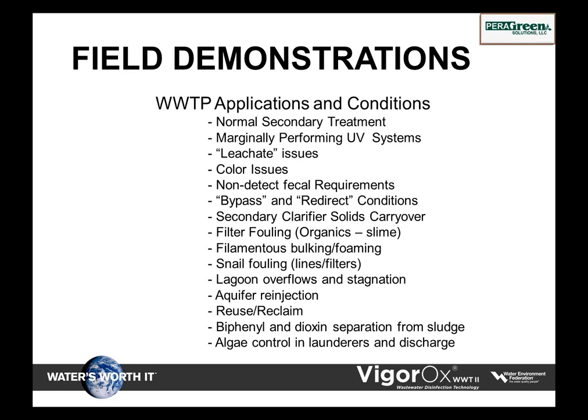Another thing we just found is that a lot of the landfills are providing leachate to the waste treatment plants to get rid of them. So they have huge leachate issues. They may dump all at once. They may feed at 100 gallons a minute. What this does, it causes a huge demand because it's a reducing agent. It will kill the PAA. Very similar, sodium bisulfite will kill chlorine, as it will kill the PAA.